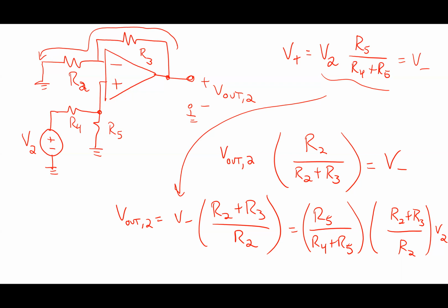And I know they're in series because there can't be any current leaving here. Right? So in other words, I'm doing a KVL and going from ground through R2, through R3, into this voltage source to ground. That's a situation where I know the voltage across the series combination, so it gives me this. Okay? So then I set those equal to each other.